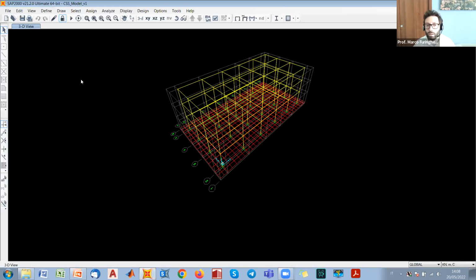Generally, there are software packages which can also handle much higher run times, depending obviously on the complexity of the structural systems that you consider. But I think that for what we have modeled, it was a fair enough runtime, because half an hour for three models with 7 nonlinear time history analyses, plus 1 for the gravity load application. But you have seen that the gravity load application is a very fast nonlinear time history analysis simply because it is just a gravity application. So there is no movement, but just some flexural deformations for the elements, and that's it. There is no involvement of the nonlinear links, which are the only nonlinearity that we have implemented within the software. So let's start by seeing all these